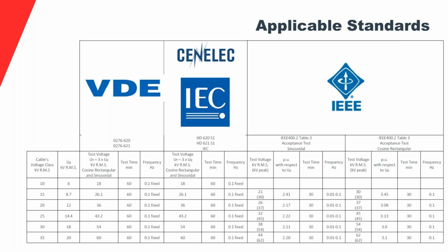Okay, now I have to find out which of the 3 phases failed, and then you do fault location and you proceed. But yeah, that is pretty much doable. It's recommended to save time, because you cut the total test time down from, let's say, 3 hours to 1 hour, as long as it's within the capabilities of the test equipment.